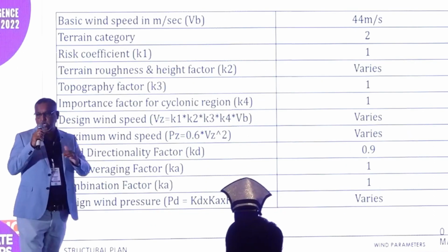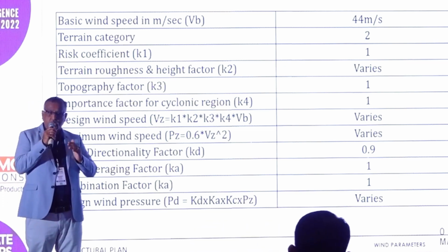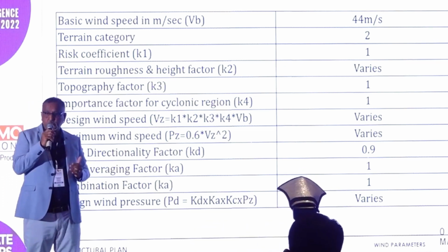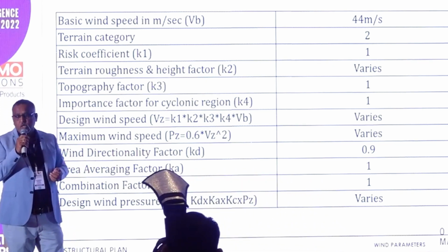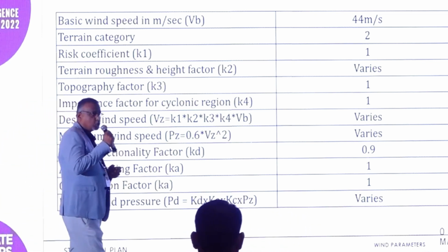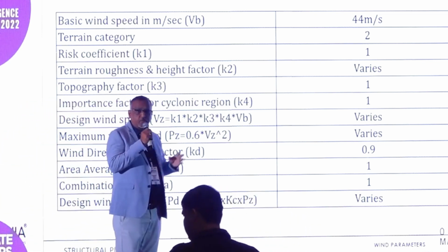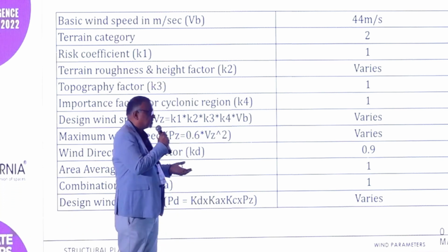Of course, as the height goes on increasing, as compared to seismic, wind forces become more critical. And again, the evaluation of wind forces needs to be very precise. And for such buildings, we recommend performing the wind tunnel test.